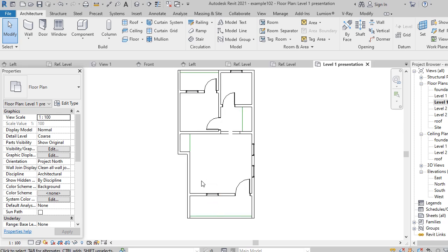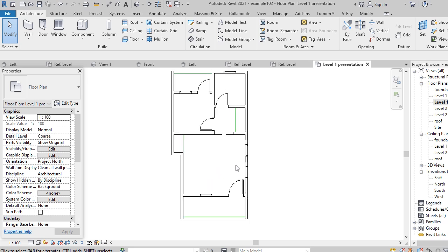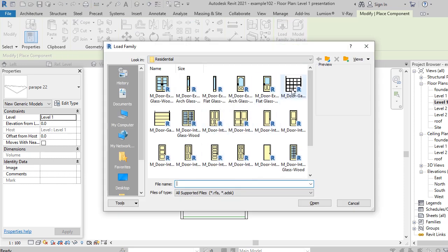At this point, you can choose to put in your televisions, all of those things for 3D graphic presentation work. All right, so to put in all of those things, let's say I want to put a chair, a couch here, all right, and kitchen cabinet. Though I may not have all the time to do all of that, but you just have to go to your components and placing components, load in family.